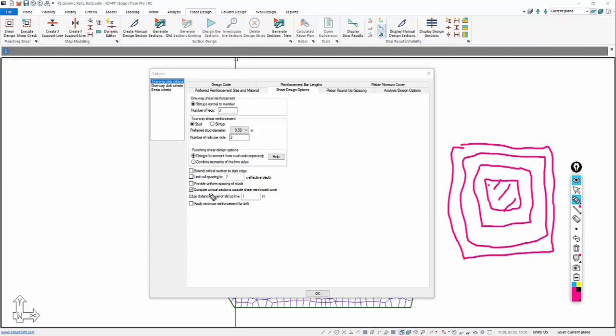The change that has been made is, when this is selected, the program identifies the last rectilinear section that no longer requires reinforcement. I'm going to add a few rails here just to show this. This is the outcome based on rectilinear sections. The program would then go back and recheck based on this shape here.